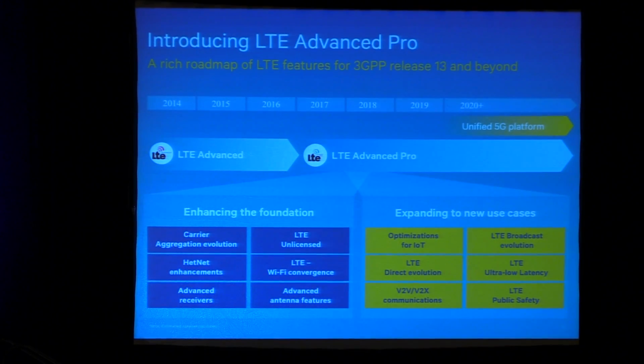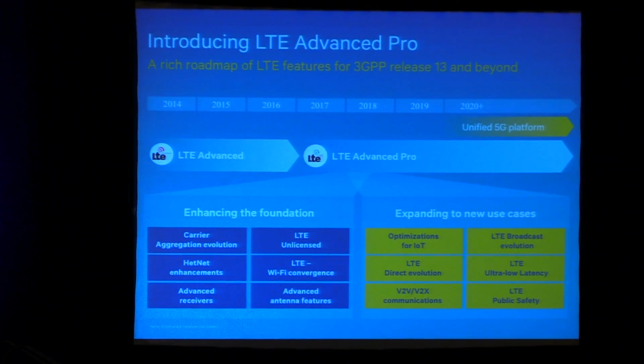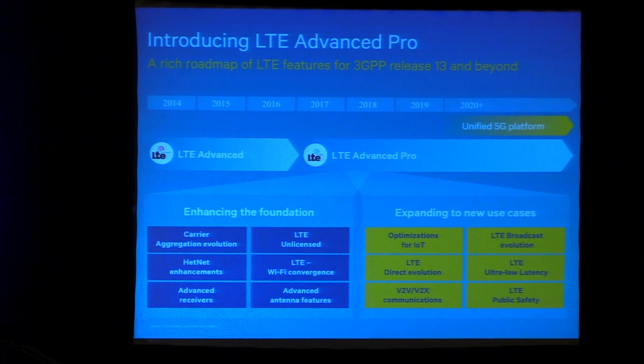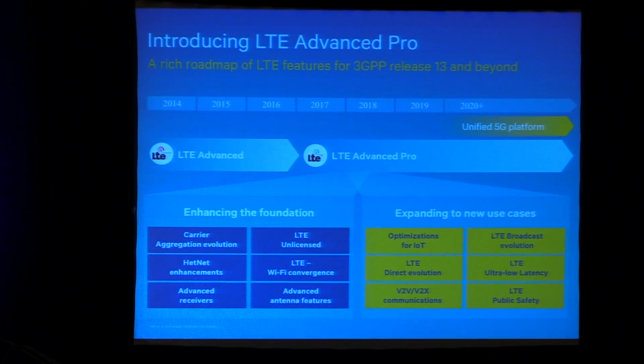So LTE Direct allows devices to discover each other at low power, and it does so around every 4 seconds. It listens, and you can leave that on 24 hours a day. The impact is comparable to standby time, so it's almost nothing in a 24-hour period. You can leave it on all the time, but it's 4 seconds. So that's not suitable for vehicle-to-vehicle for safety applications, but we can take that design, reduce the latency and define it as V2V. So that's an example of one of the things we're doing as part of this improved LTE Advanced.